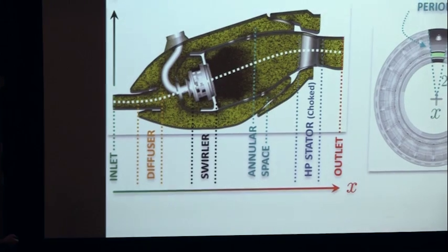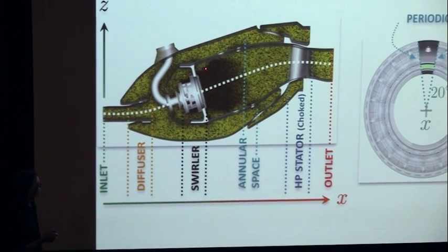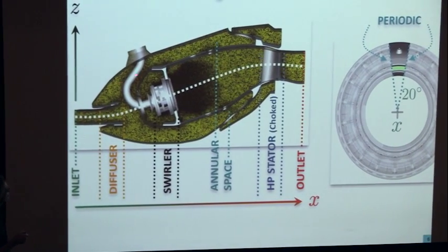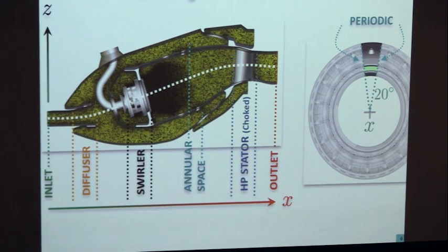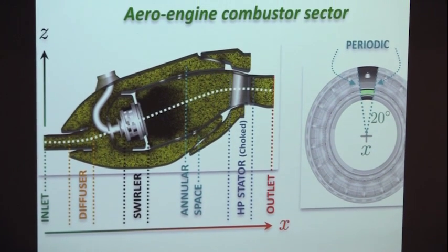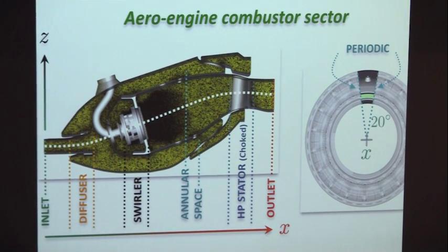Now, which walls are we talking about? In an engine, you have 2 types of walls. You have the casing, where you have what we call cold air. Be careful when you say cold, it means 700 K, okay? Not Fahrenheit, okay? And then in the engine here, you get more than 2000 K. And so you have your combustor walls here, which is the first problem. They must survive. And here you have the blades here at the outlet. They must also survive. So all of this has to be controlled.